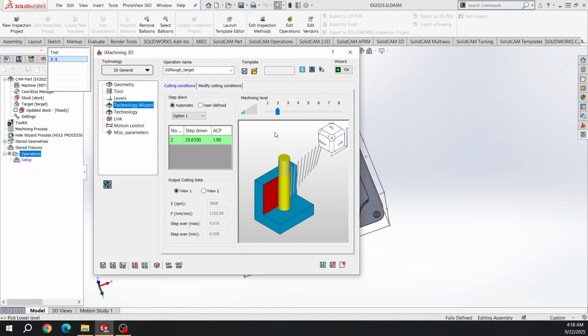While you are physically making the cut, you can decide whether we can go to higher levels or lower levels. You can see spindle rate and feed rate, we can't manually edit them. Once you adjust this level, only then is it going to change. What happens in iMachining is it calculates according to your tool and your material.